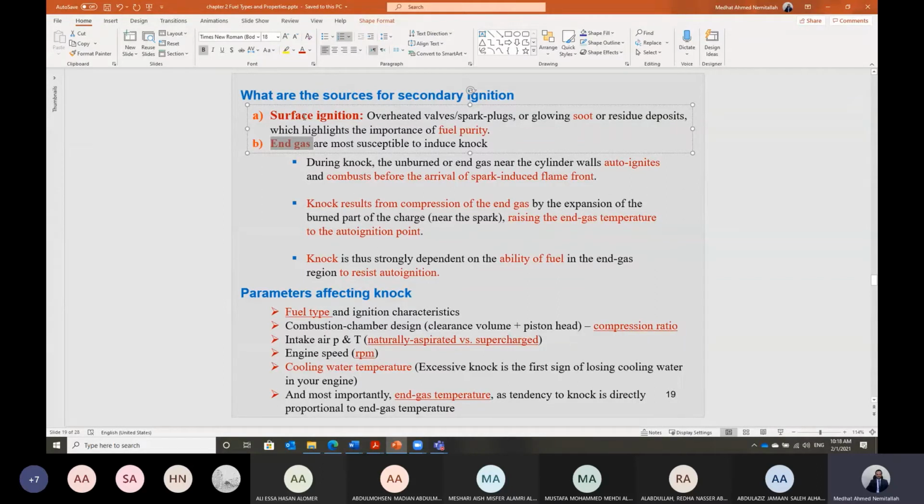Another source of ignition inside the cylinder is if we have some carbon deposit on the spark plug or on the intake valve, or in some cases, with some new versions of gasoline injection systems where we inject the fuel inside the cylinder, on the injector, which will be inside the cylinder. If we have some carbon or soot from the combustion accumulated on the intake valve, the spark plug, or the fuel injector, this carbon has a higher specific heat, a higher specific heat at constant pressure.